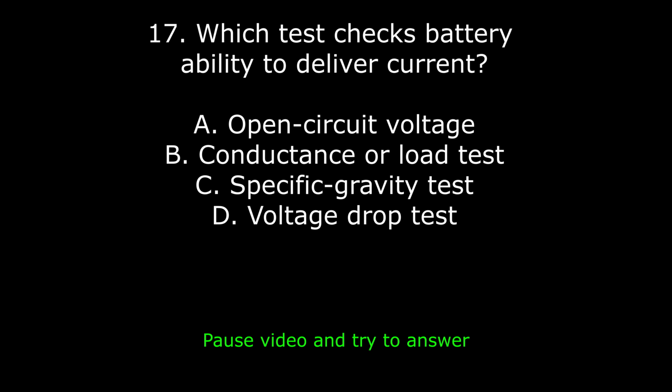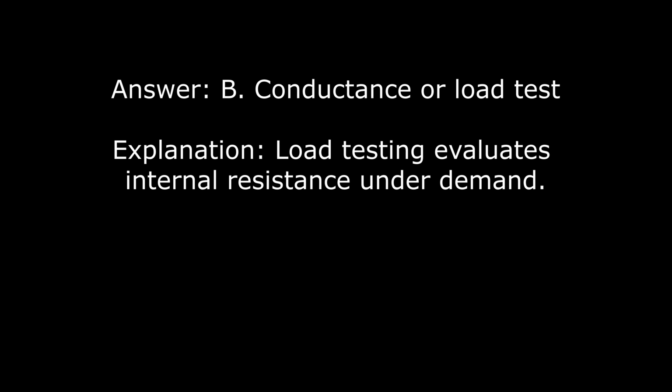17. Which test checks battery ability to deliver current? A. Open circuit voltage. B. Conductance or load test. C. Specific gravity test. D. Voltage drop test. Answer: B. Conductance or load test. Explanation: load testing evaluates internal resistance under demand.